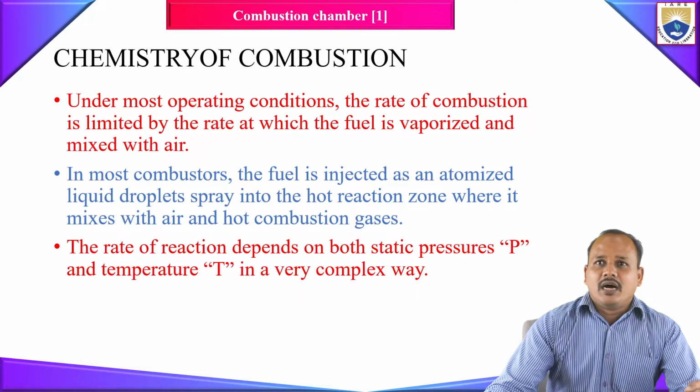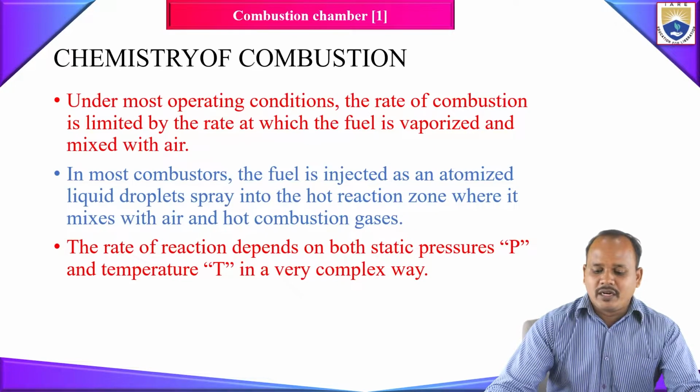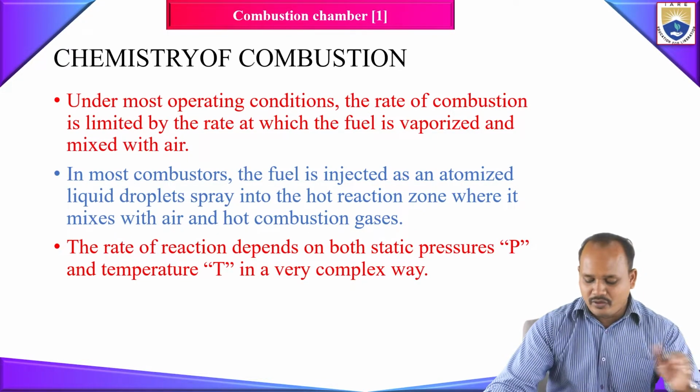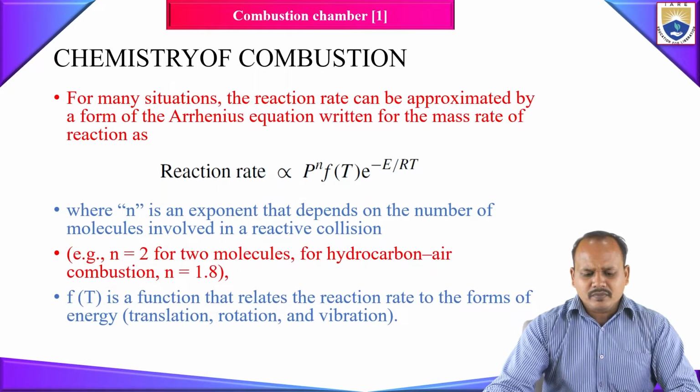Even if you are going to inject your fuel in droplet form, the reaction rate, that is the rate at which heat energy is released due to the combustion process, mainly depends on the static pressure and static temperature inside your combustion chamber. Basically, static pressure and static temperature depend on how much pressure and temperature your flow has coming out of your compressor.